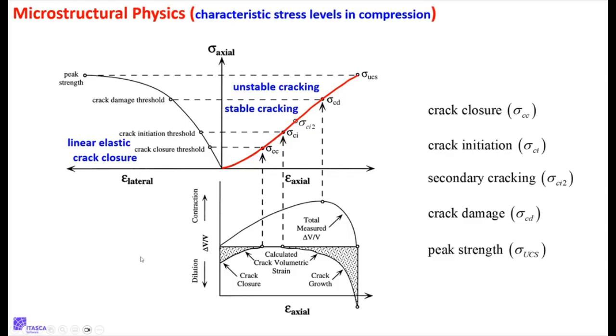A typical test like this might take 30 minutes because you want to have it be quasi-static, meaning we don't want to worry about the effects of rapid loading. If you load something really fast, that means you're accelerating the material, and that means the force pushing back on you is higher than it would be if you loaded it slowly.